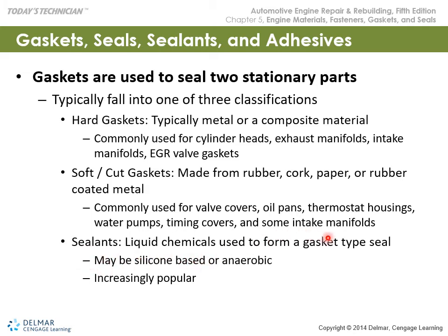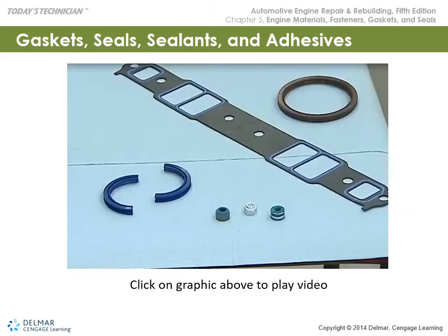Sealants, liquid chemicals, RTV, which is your silicone base, and your anaerobics, which harden in the absence of air, are specified in certain applications. Okay, we're not going to get the video on this one, but here we're showing some half rounds that'll go into a valve cover to a cylinder head. Here we're showing an intake manifold and a seal, and we got some valve guide seals here are shown.